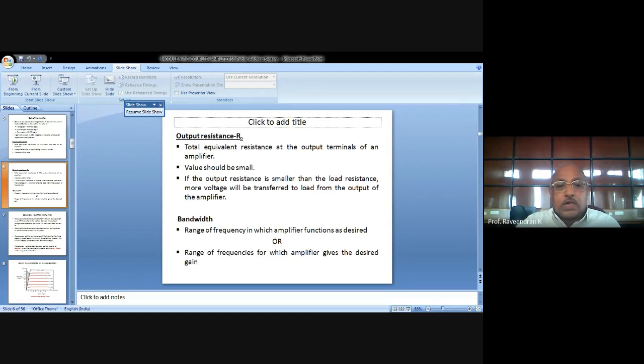And of course, to maintain the operating point stable by keeping IC and VC constant so that the transistor will always work in the active region. So the biasing circuit always maintains these three conditions, or these three needs are satisfied: to fix the operating point at the middle of the active region, to stabilize the collector current against the temperature variations. Of course, the temperature will vary definitely, but that will not reflect upon the collector current, and the operation of the transistor must be stabilized.